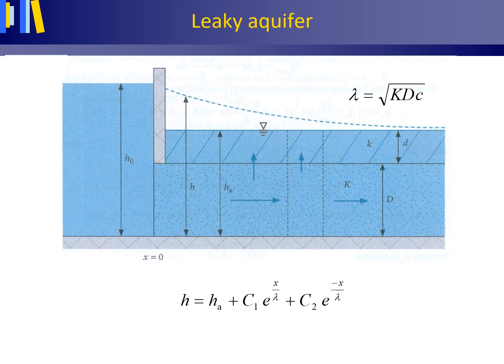In this example of Het Hollands Profiel, the right boundary condition is taken at infinity. At infinity, the horizontal groundwater flow through the aquifer has diminished to 0, and the difference in hydraulic head between the aquifer, the dashed line, and the polder, HA, has also diminished to 0, and thus the upward seepage through the confining layer also is 0. We call this setup of Het Hollands Profiel an infinite polder.